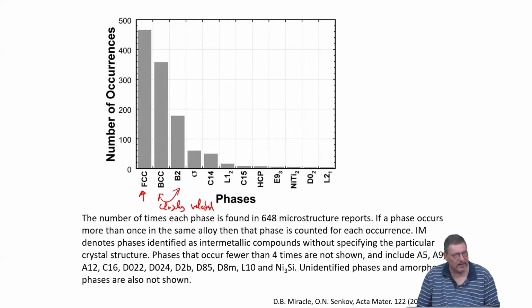So when you think of trying to make a high entropy alloy with a specific structure, and you think about choosing which elements to choose, think of the radius in solution. How is the mixing enthalpy between this element you might choose to add to a given number of elements to make a solid solution alloy?